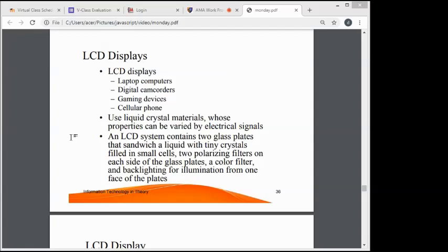A backlight in a liquid crystal display provides an even light source behind the screen. This light is polarized, meaning only half of the light shines through to the liquid crystal layer. The liquid crystals are part solid, part liquid, and are twisted by applying electrical voltage to them. They block the polarized light when they are off, but pass the red, green, and blue light when activated.